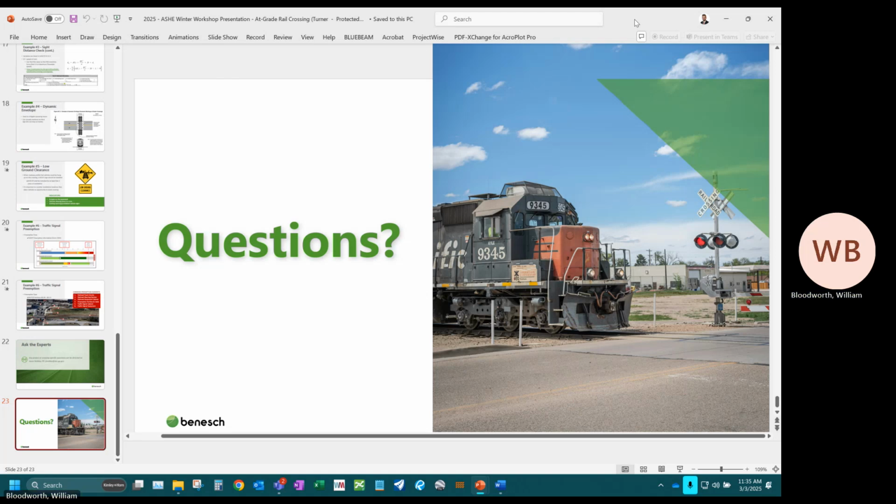Exactly. And the other piece is maintenance has to go put back the epoxy if they resurface the road, and often they just can't afford that, or it's not sourced in a very economically feasible way to get into America, versus the lightweight aggregate. There's a distributor of that in North Georgia, so it's much easier to get. And if you're curious, that lightweight aggregate is synthetic volcanic rock. Technically, if you're in Hawaii, they don't need it. They can just use the normal aggregate there.